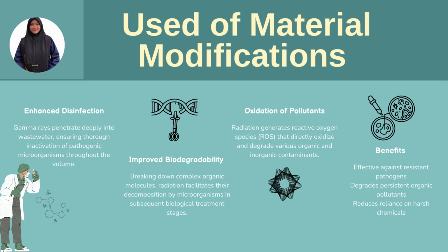First and foremost, material modification is used to enhance disinfection. Gamma rays penetrate deeply into wastewater, ensuring the thorough inactivation of pathogenic microorganisms throughout the volume. Secondly, it improves biodegradability by breaking down complex organic molecules. Radiation facilitates their decomposition by microorganisms in subsequent biological treatment stages.